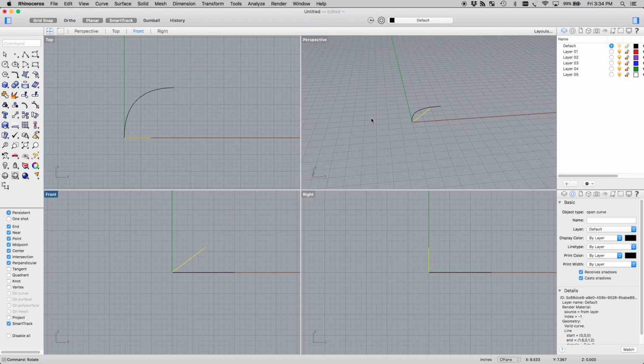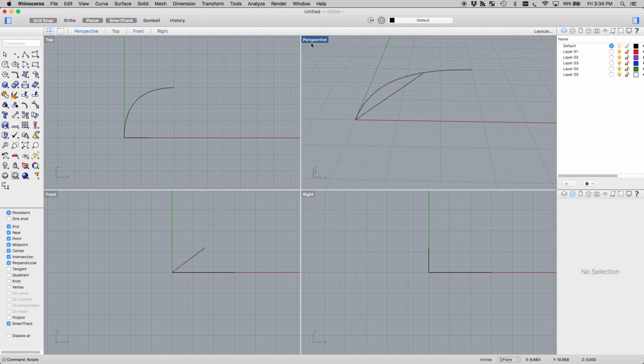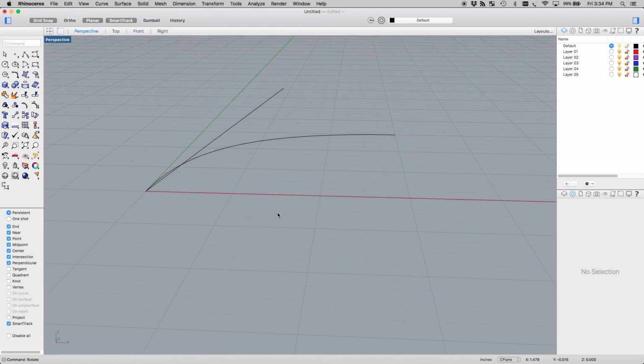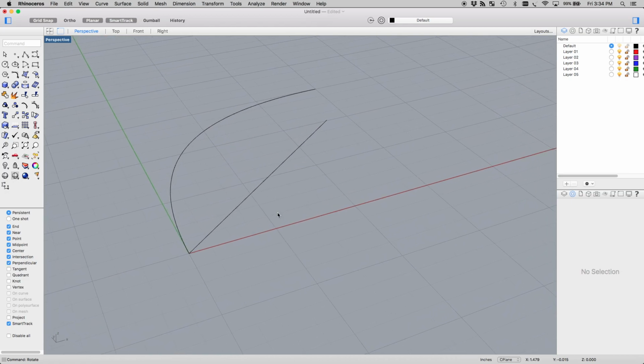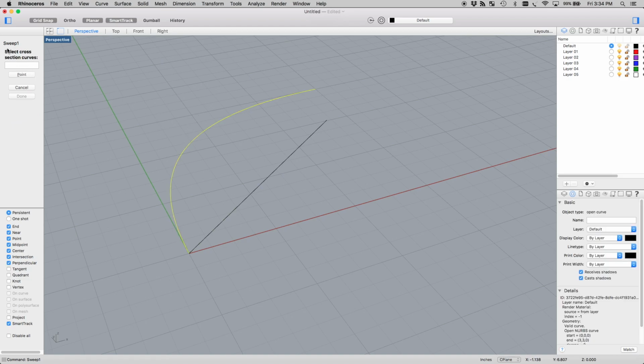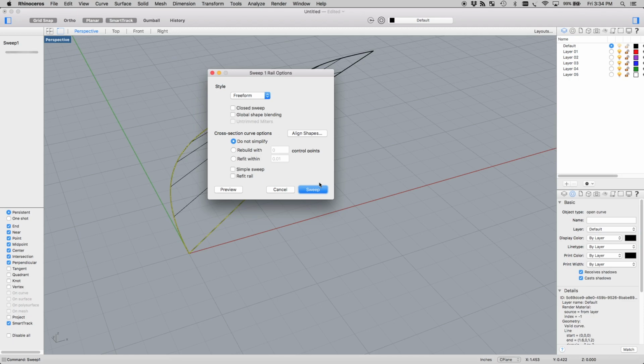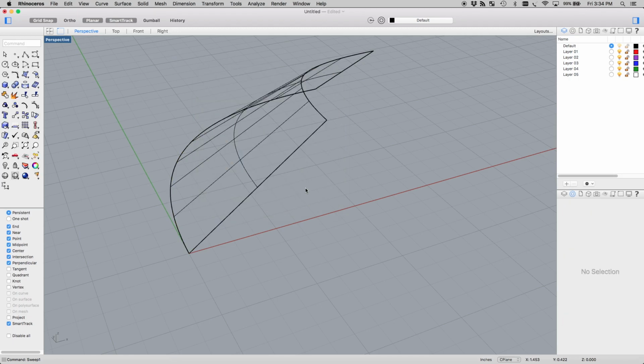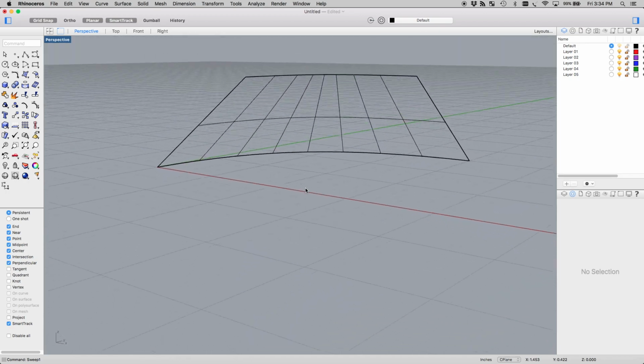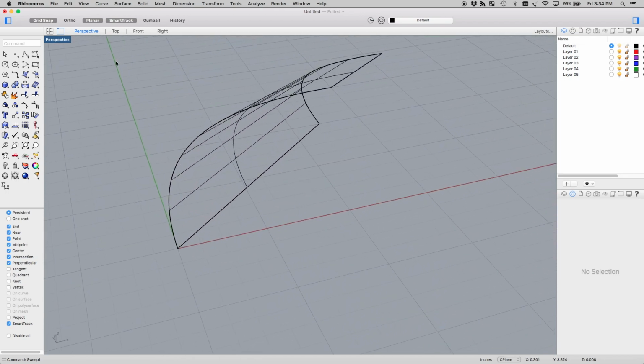Lastly, let's see a sneak peek of what Rhino can do in 3D with the Sweep 1 command. Here, we'll select a rail and cross-section curves, plural if desired, to sweep to create a surface. We won't get into the nitty-gritty of all the details of sweeps here though, as generally for our purposes, the initial suggestion will work just fine.